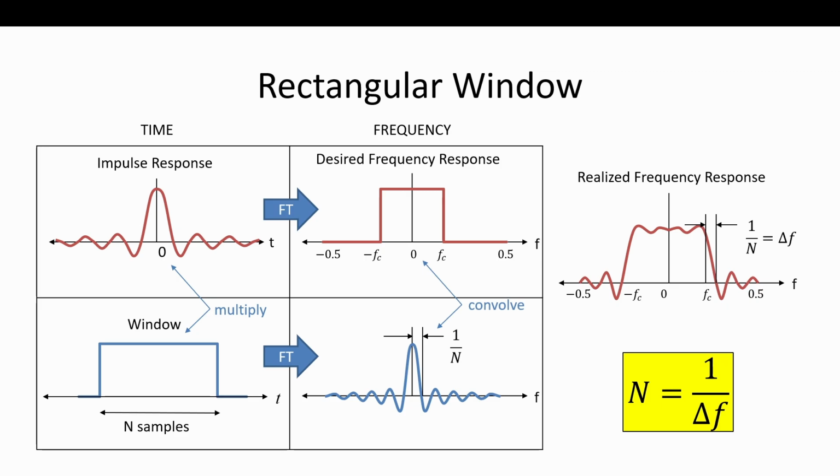So we had this rectangular window, and what did we see? Now you can see what happened behind the scenes, how it got smeared. The top one says we had this impulse response, our perfect impulse response, which we can predict. We know we want a rectangular function in frequency. We know that's a sinc, very easy to compute every sample on a sinc. So we can get the exact values of this impulse response.